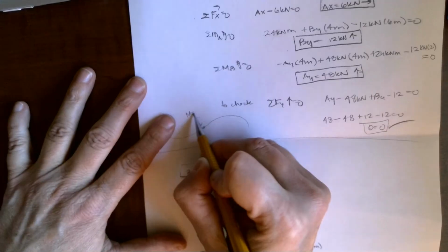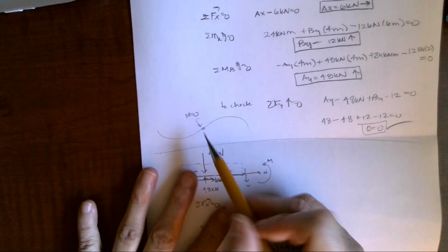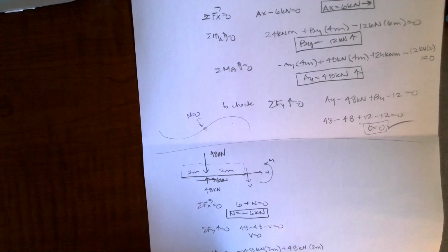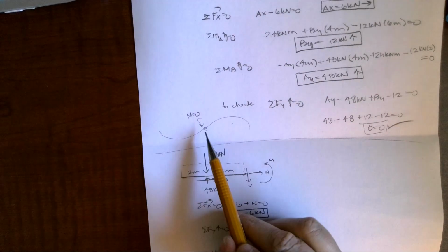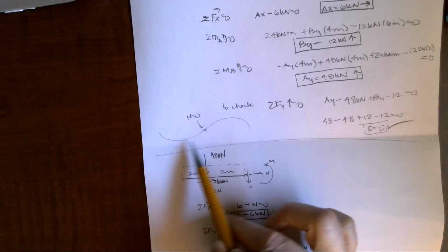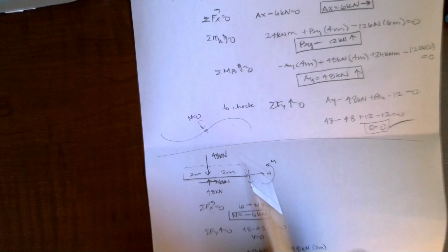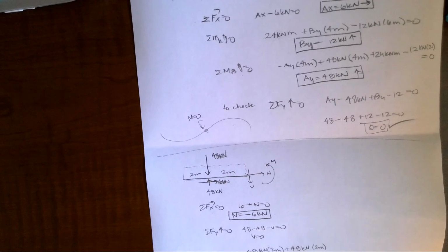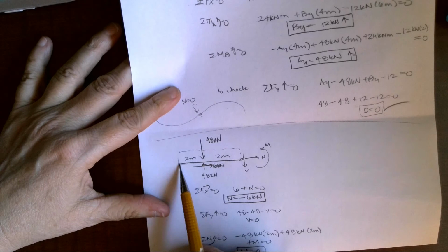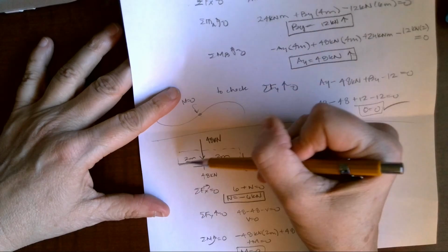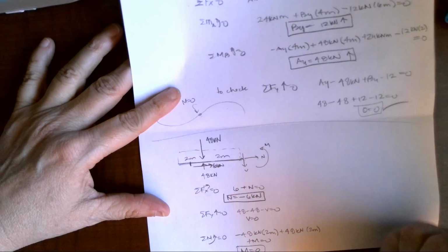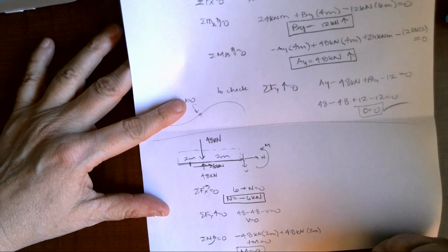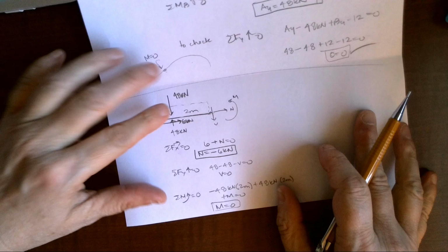And it's also called an inflection point when you move into strengths and structural analysis. It's where we change curvature. It's where we change behavior from positive to negative. And so, again, that's okay that that moment equals 0. It's just telling us that we have a transition happening in that part of the beam. And it doesn't mean that it's 0 all the way across. If you wanted to go back and calculate the moment here, 1 meter in, you would find you actually had a moment. Okay? So now let's just go ahead and cut it from the other side.